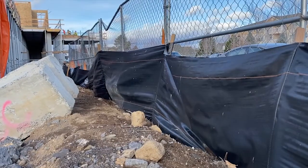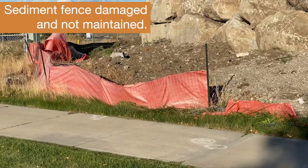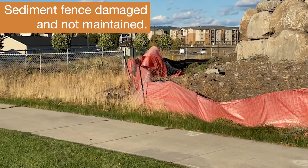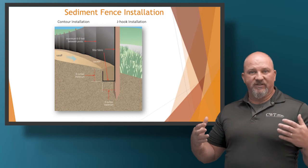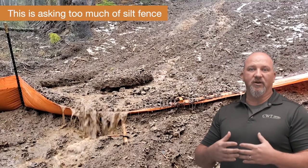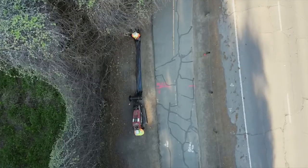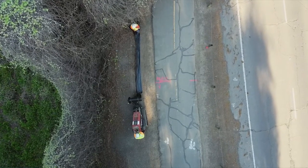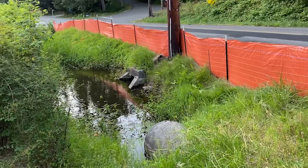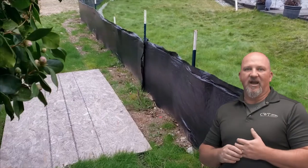And I will say that if you're relying on sediment fence to be the only thing that manages your perimeter, that project better be relatively small or you're going to have some significant challenges moving forward. Just like castles build moats and walls, we're trying to do the same thing on our project by creating separation between what could be coming to us and preventing what is on our site from leaving. Installation of these sediment fences requires that you're trenching them in and burying the tail into the ground all the way to the bury line, so that you're not seeing the bury line when you walk by.